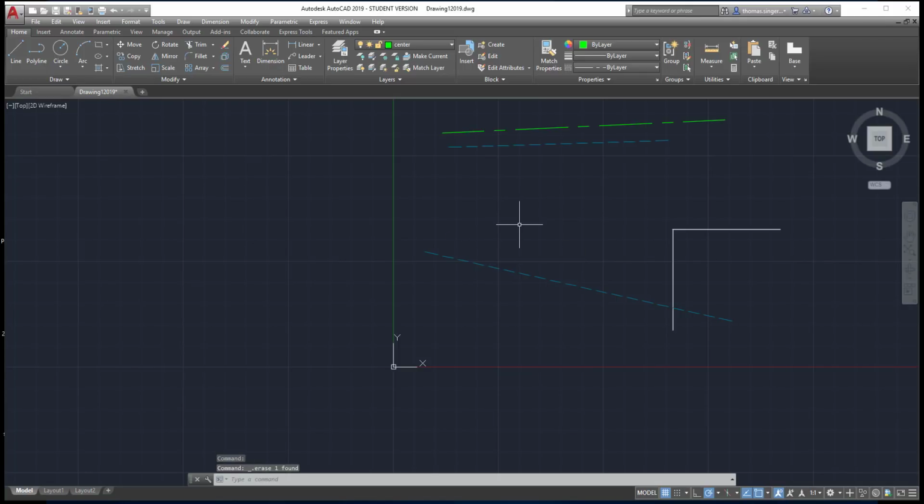So in this video, I've showed you a little bit about how to draw lines. Remember the point and shoot method, where we can point a direction and then type in the distance, and it works. So I can change the angle by using the polar tracking. Object snaps to connect to existing objects using the green icons. And like I said, point and shoot.